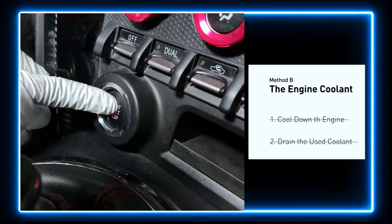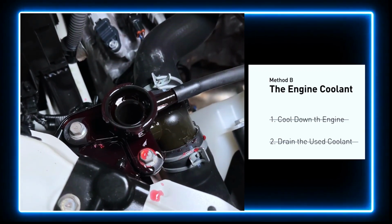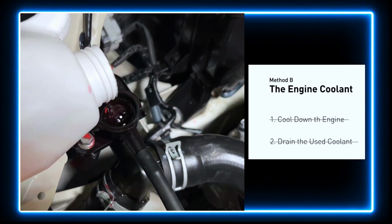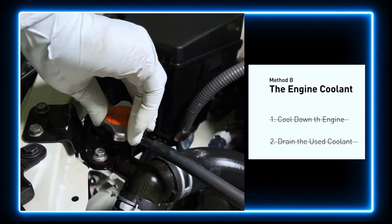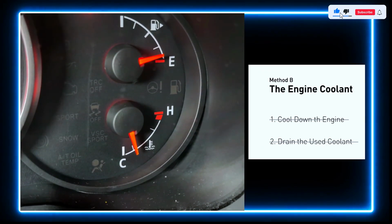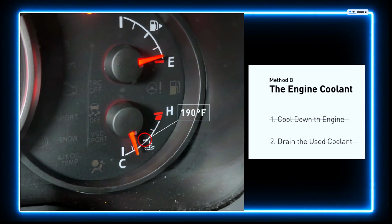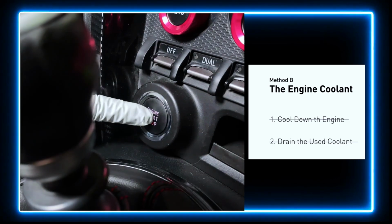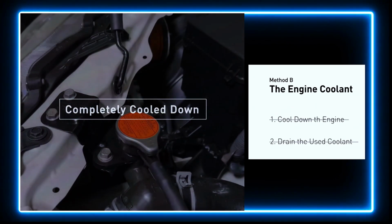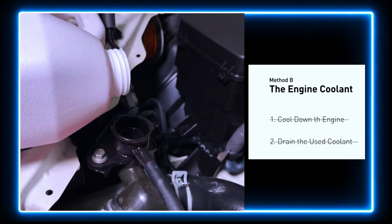After filling, start the engine and let it idle for a few minutes to let the system purge all the air out, and then add coolant as needed. Replace the radiator cap. Closely monitor the coolant temperature gauge on your dashboard. Once the coolant temperature reaches 190 degrees Fahrenheit, turn off the engine. After the engine has completely cooled down, remove the radiator cap and add coolant to its full level.